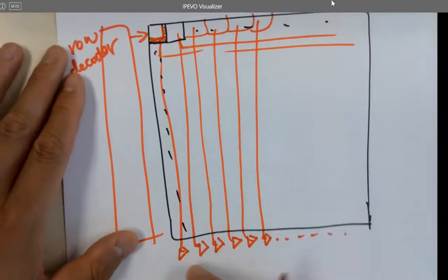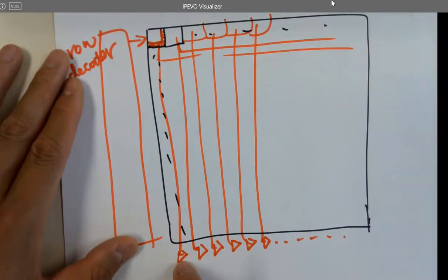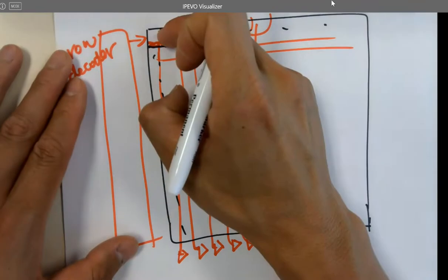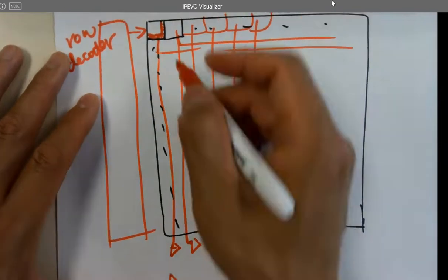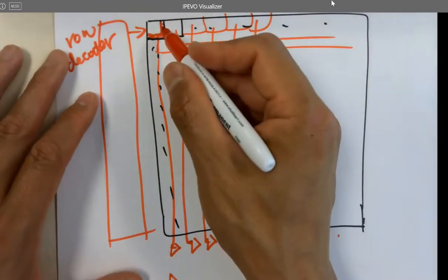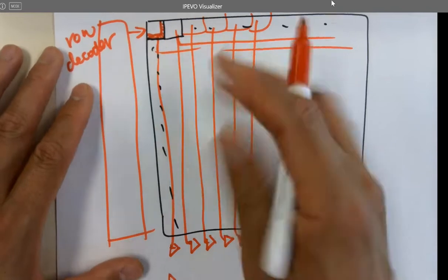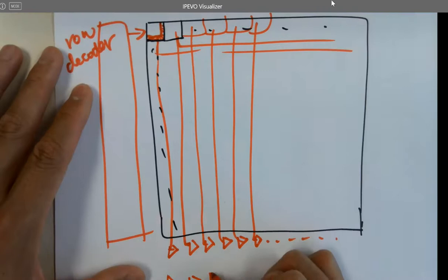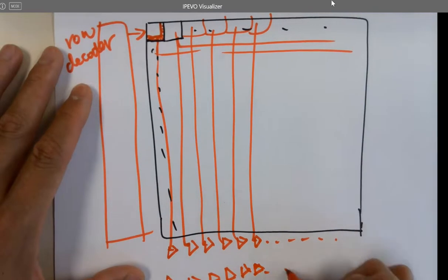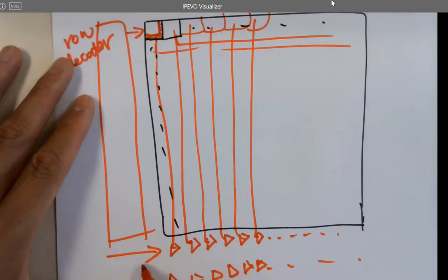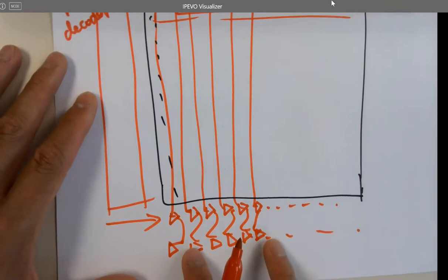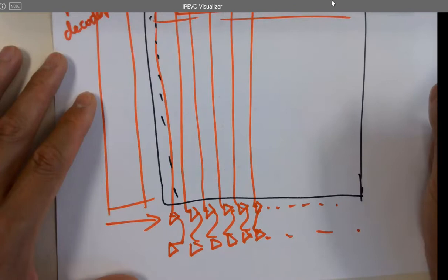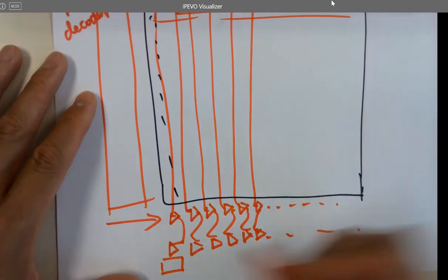There might be some designs that have these transimpedance amplifiers inside, but what they definitely cannot do is put an ADC for each pixel. It's going to be a million ADCs for the whole image sensor. No, they just have one row here, right? And whenever it's done, you activate it and send it to the ADC to convert it to a digital signal. There must be a lot of registers to handle that, different bits, right?